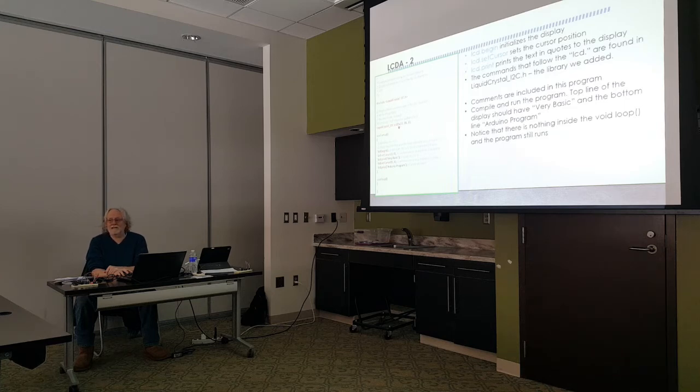So you can put a lot of devices on an I2C interface. You put a temperature sensor and a humidity sensor and a speed sensor and who knows what else. And because you're only on two wires, each of them needs its own address. So that's what the 0x27 is, hexadecimal 27.